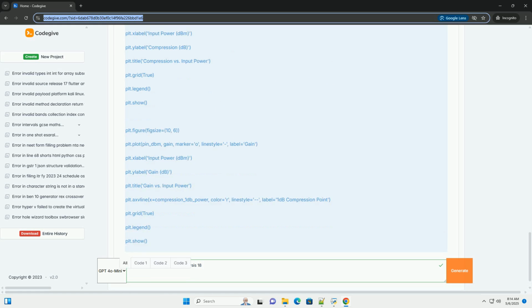3. Numerical issues. Adjust simulator tolerances. In your simulator settings, try tightening the tolerances for convergence, for example set smaller voltage/current tolerances. This can help with convergence problems at low signal levels. Initial conditions: for transient simulations, ensure you have reasonable initial conditions to help the simulator start correctly. DC solution: make sure your DC operating point is stable and correctly biased.